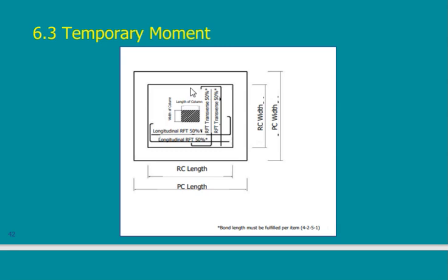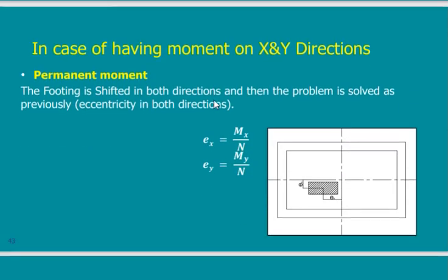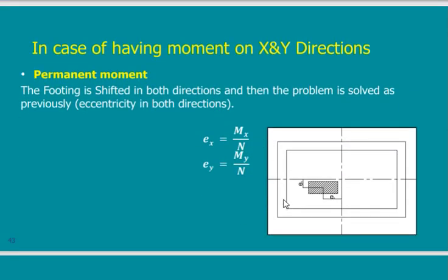I don't really need all of this amount, so I'm reducing it. It's a way for cost reduction, and that's all, because I don't need all the amount of steel to reach from the start till the end of the reinforcement. Both are okay. Usually we do 50% this shape and the other 50% of the other shape. So we use this in case we have a very high amount of steel and we want to make some cost reduction. If I don't need to do cost reduction and the amount of steel is okay, then I can use the U-shape.